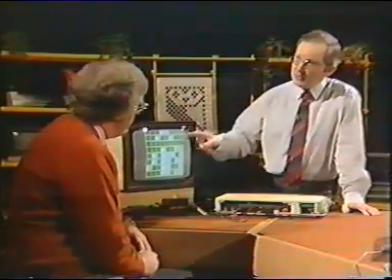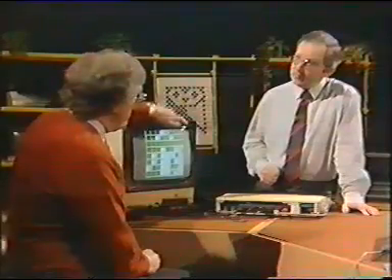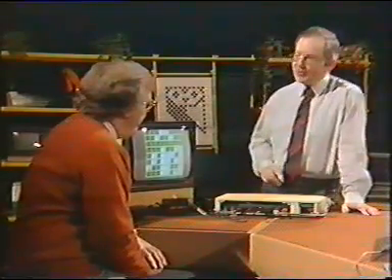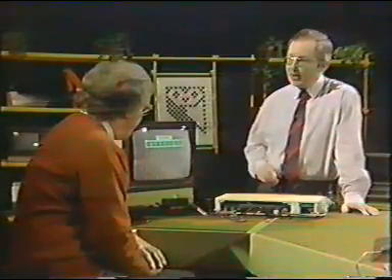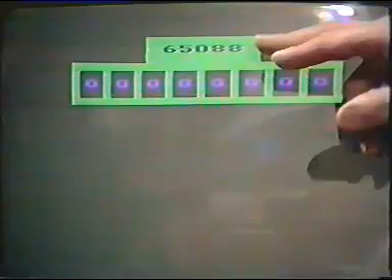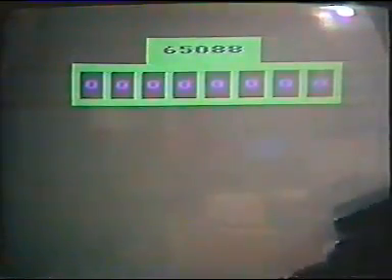Remember that we had a memory map, 64K memory map, and we used this display to illustrate. Right, each one of these is a byte running across with 8 bits, and there's about 65,000 in the machine itself. Well, what happens inside the computer? Well, we've got a couple of those addresses set aside, not for RAM, random access memory, but in fact for input and output devices. And here's one particular address, 65,088, which in fact is an input connection.